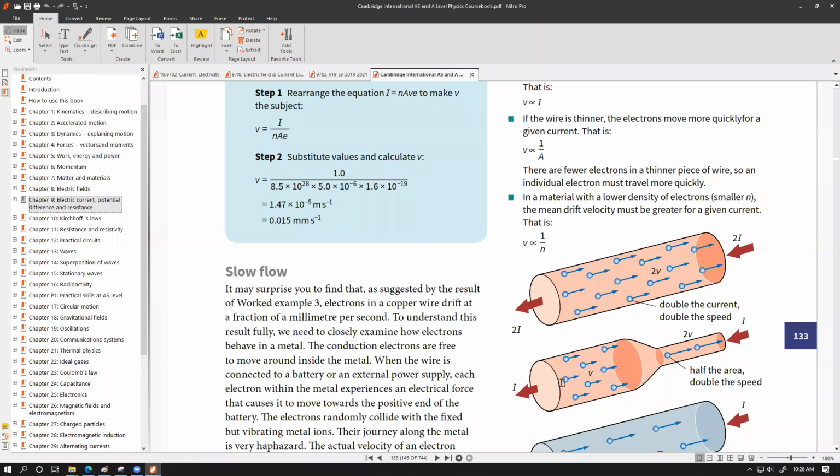Why does the water squeeze out really fast? This is because inside the pipe the water is flowing through a large tube, but when the hand shower is open, all of those very tiny holes push out the water at a very high speed. So the flow rate has to be the same. The amount of water volume per second, or kg per second, that flows into the hand shower tube has to be the same as the amount of water that flows out of all of these small pipes.